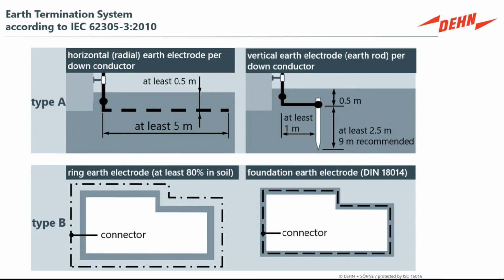So grounding systems. In the IEC methodology, we have a couple of ways to look at this, type A and type B. What we find is that this is essentially a single isolated ground rod, which sometimes happens. Not always can they be bonded together around the perimeter of a structure. It just can't happen. In some legacy city urban environments, you're not going to be able to dig up the street and put up a buried type B ring around the structure. So it's the IEC methods, and you see this as well in the NEC methods. It allows for what essentially becomes a buried electrode.